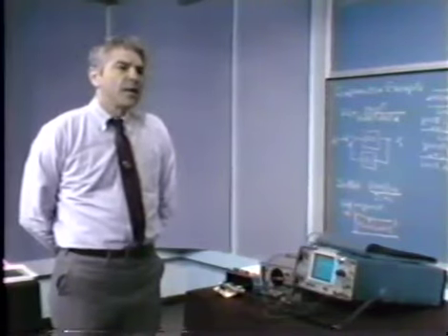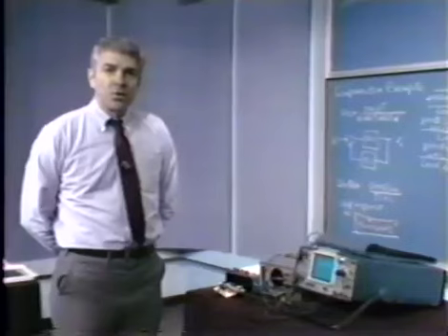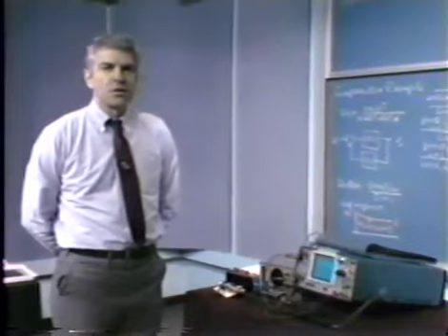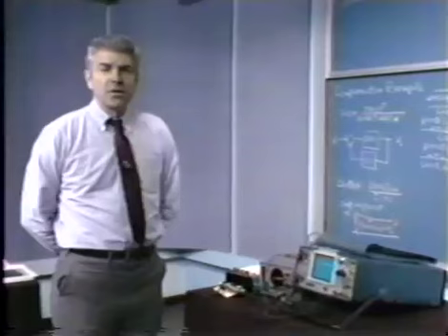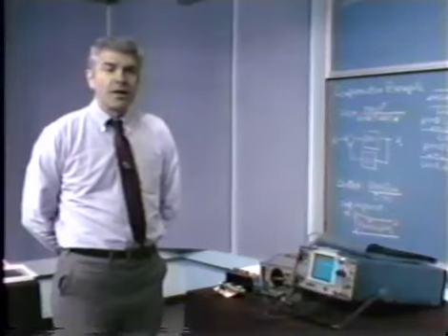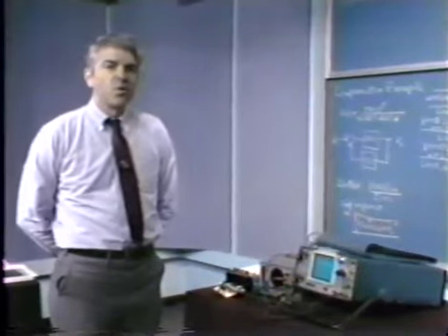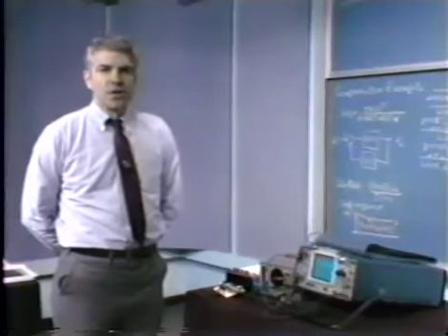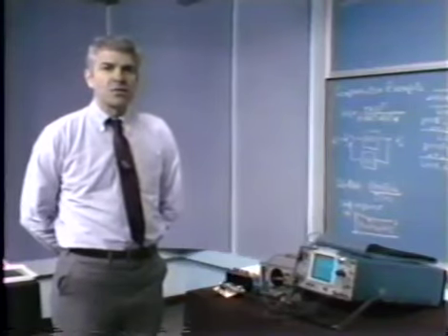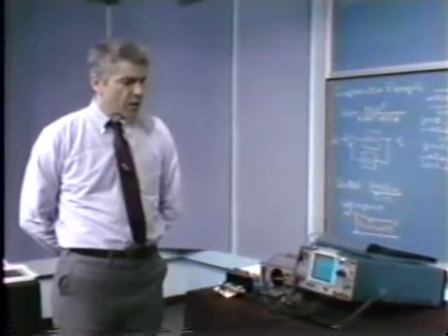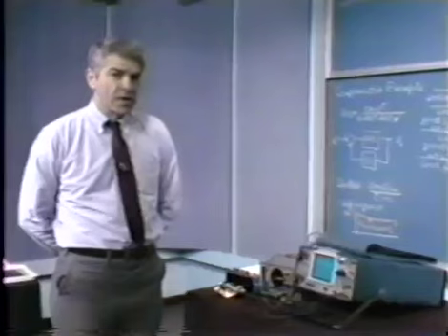the system. Now suppose we had a system that had 0 phase margin and a crossover frequency of 4 kilohertz. Under those conditions, the step response would be a sinusoid or a cosinusoid at 4 kilohertz. We'd put in a step, if we had a system that had 0 phase margin, 180 degrees of negative phase shift associated with the AF product. Why, we'd find that the system would give us an oscillation at precisely the crossover frequency in response to a step. So under those conditions, we'd get a 4 kilohertz constant amplitude oscillation.